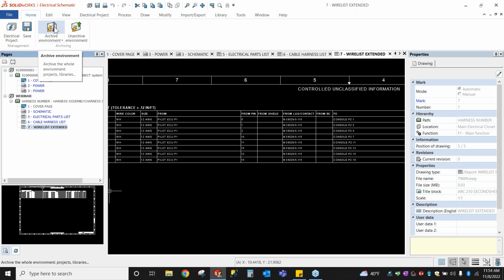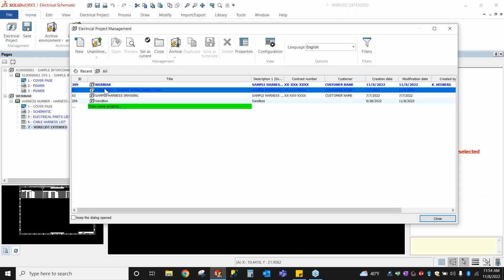And then each project, whenever I'm done with it for the day or just done with it, I will archive that project and store it in PDM. So I have a whole workflow process document that I chose to do that. But I do store all of this stuff in PDM because then we get different versions of it. So if we change something that should not have been changed, we can go back to a different state in time.